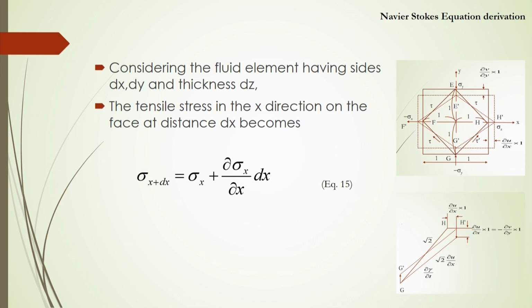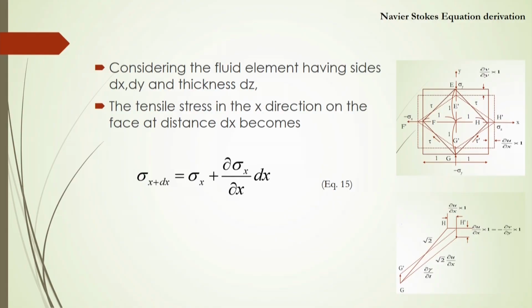And if we consider the fluid element having sides dx, dy and thickness dz, the tensile stress in the x direction on the face at distance dx will become sigma x plus dx, that will be equal to sigma x plus dou sigma x dou x into dx. This will be your incremental tensile stress. So at this x plus dx, you can obtain the tensile stress from equation number 15.